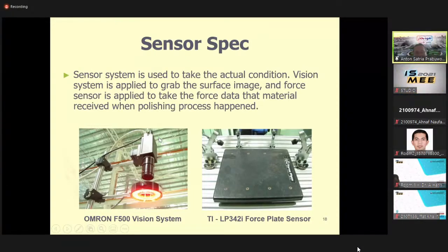This is a high-speed CCD camera, charge coupled device, and we also put an LED system to minimize the blur effect due to the metal surface, because the object of the inspection is metal, so the surface reflects the lighting from the environment. So we minimize reflection by installing the LED circular lighting in this process.